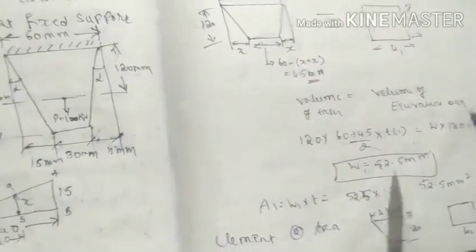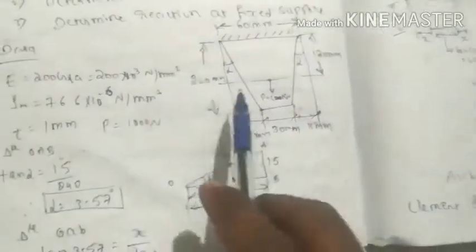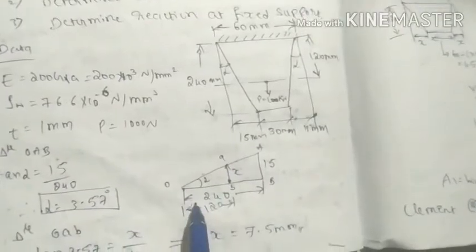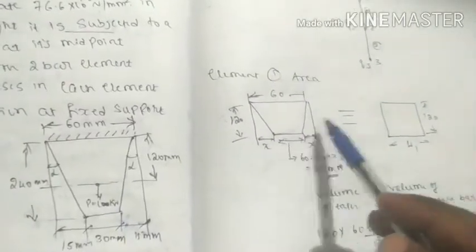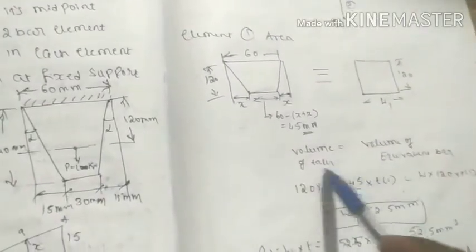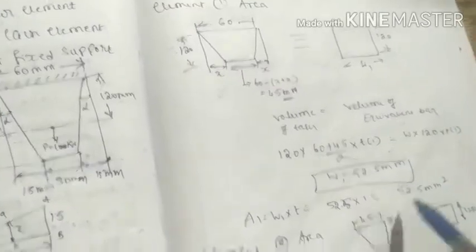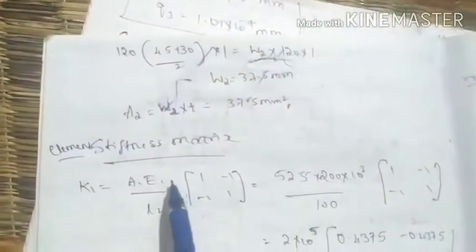So it is the same thing, but you should not go with that approach, because it is particularly given. We need to find the taper angle, calculate the taper angle, then calculate x, then calculate the middle width, then take both sections separately, equate the volumes, find the width of the two sections separately, and finally find the area. So the rest of the steps are the same.